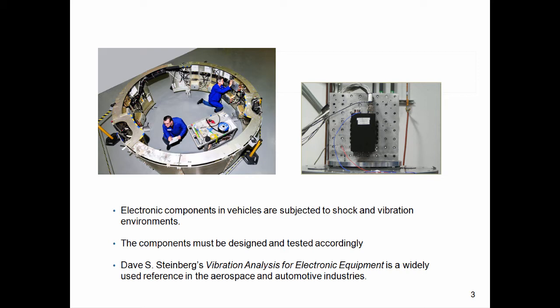But anyways, these electronic components during flight will be subjected to various shock and vibration environments. Some of those will occur during the liftoff, and another excitation phase of interest is when the vehicle goes transonic and encounters its maximum dynamic pressure condition. These avionics boxes must be designed and tested accordingly.